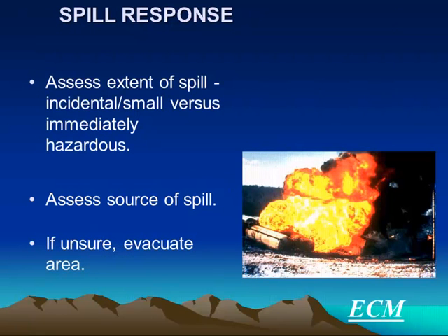Okay, if you see a spill, like if you spill a little antifreeze, go ahead and clean it up so the guy walking next to you with a box doesn't slip on it. But if you walk into the shop in the morning and there's a couple inches of product in your service bay area and you're not sure where it's coming from, just evacuate the area. Let the experts come in. If you can't tell the source of the spill or if it's safe, just evacuate.